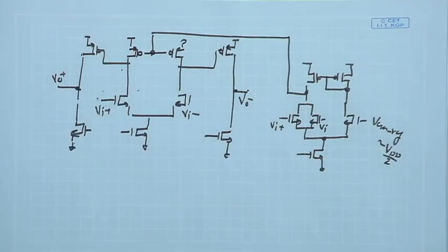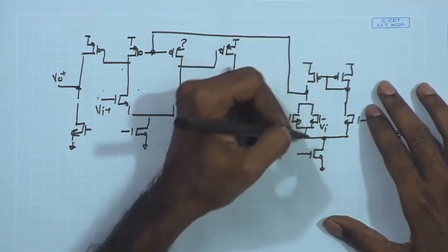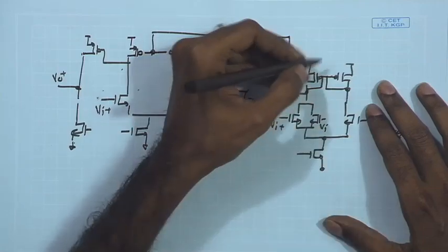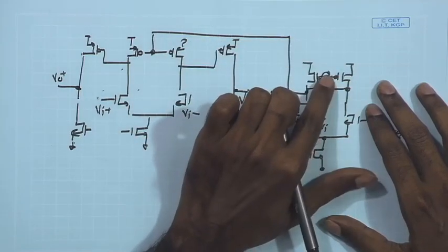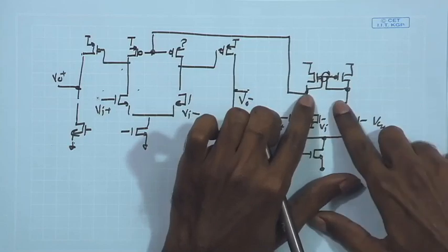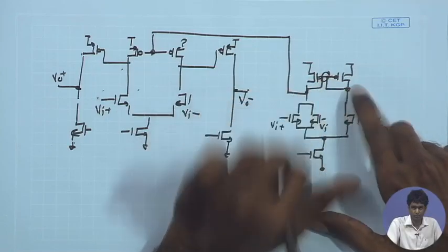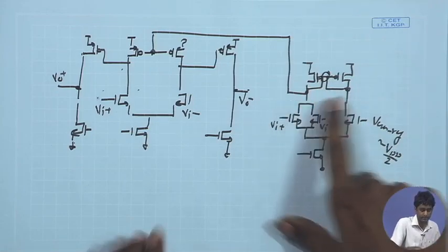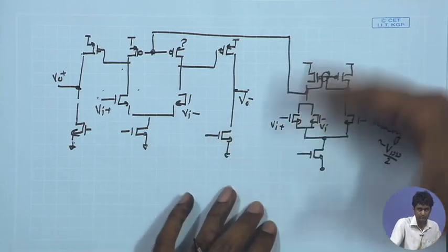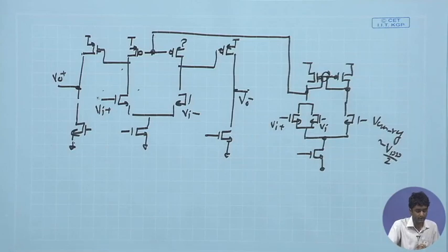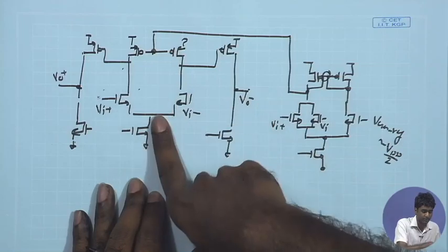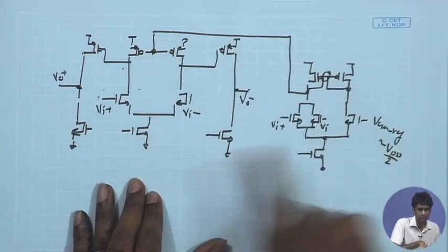So, this is what we discussed, and we also suggested that let us get rid of the current mirror load and have a diode connected load, disconnect this node. Of course, for the diode connected load, you have to disconnect this, otherwise you are shorting both the outputs. So, you have to disconnect this central connection and make both of them diode connected, so that the gain of this stage is given by GM1 upon GM2, and as a result you have the overall gain of the common mode feedback loop given by GMRO of the two stages. This is going to give you unity.